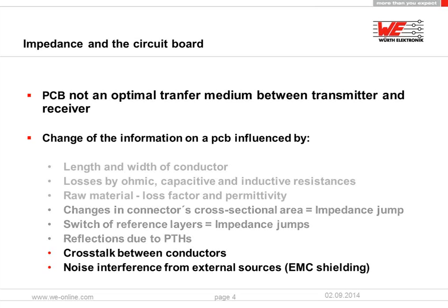So the topics are impedance power matching, caring for the timing issues, and avoiding reflection as far as possible. This example shows a detail from a USB 3 design. We can see some differential pairs, and the shape is to match the timing. So the lengths of this differential bus should all be equal.